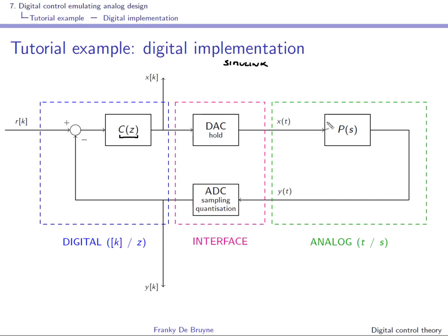So you'll have to use the continuous time transfer function, the zero order hold block, and here the rate transition, and you'll be able to obtain the output at the sampling instants, but also the inter-sample behavior. If you want to work in Matlab, then you'll have to look at the process from this input over here, which is x of k, and this output y of k.